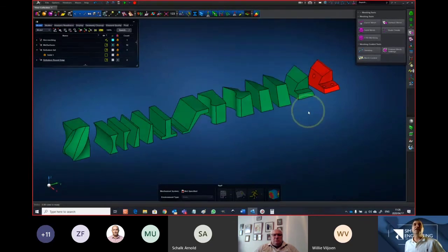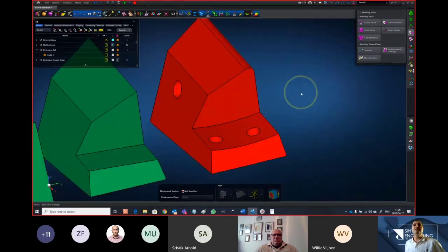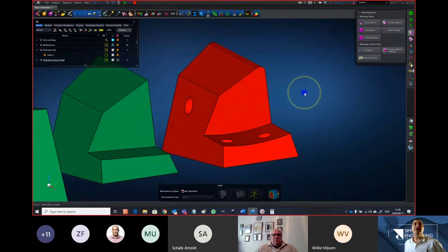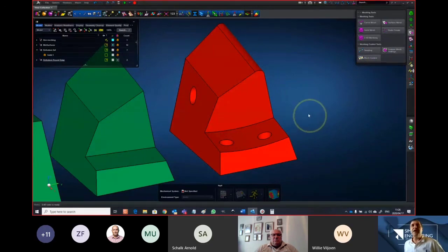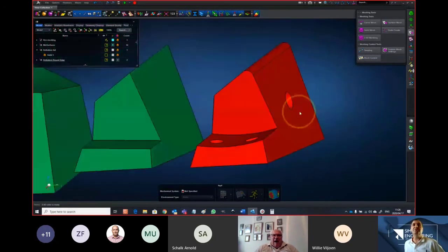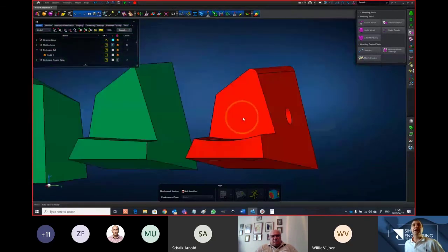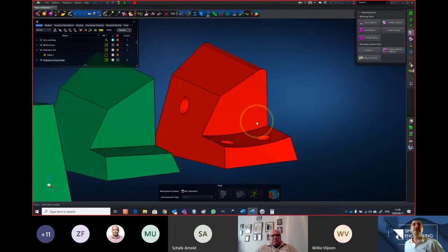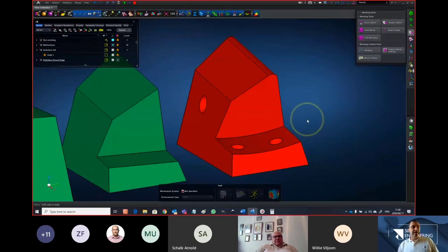And the reason you will want to have this active in a different tool is the ability to now manipulate the geometry so that we can actually hex mesh this body. Now, as you can see, the reason it isn't hex meshable is because of all these features following in different directions, which doesn't resolve in a simple way to hex mesh it, or at least at this stage Apex can't identify how this thing is hex meshable, although they've progressed quite far.